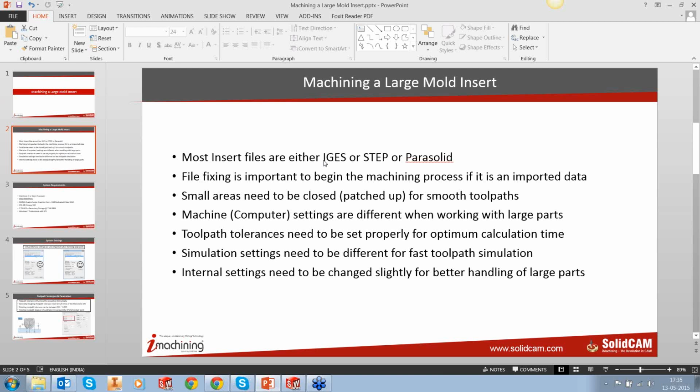You know the problems involved, especially in converting the IGS files into SLDPRT. Most of the time, SolidWorks does a pretty neat job in converting it and giving a much better part file. But there are instances where you get into problems where some of the surfaces are not good enough for machining. They could be good enough visually, but they're not good enough for machining, which then SolidWorks gives up some tools which you can use to correct those surfaces.